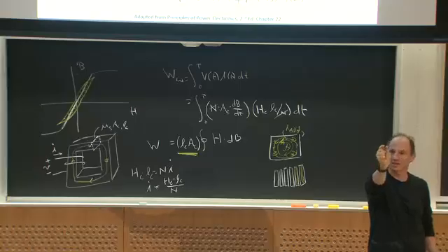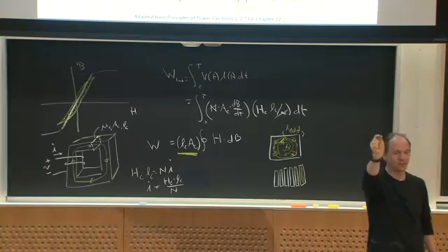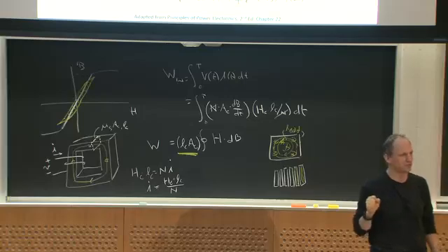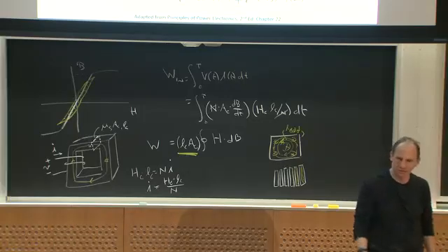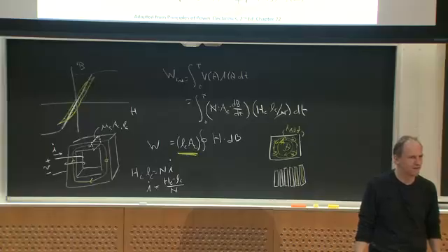How do they size the skin depth of those laminations? How do they size the lamination thickness? They ask what the skin depth in the steel is, and they make the lamination thin compared to that. Any questions?